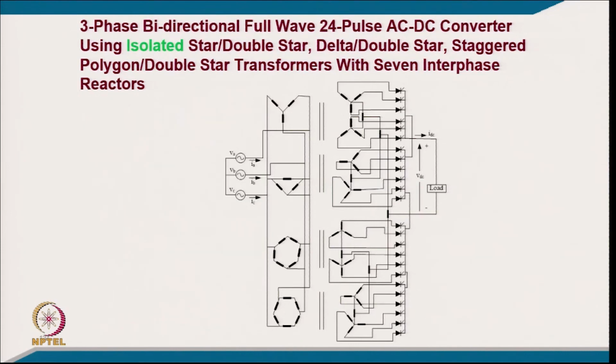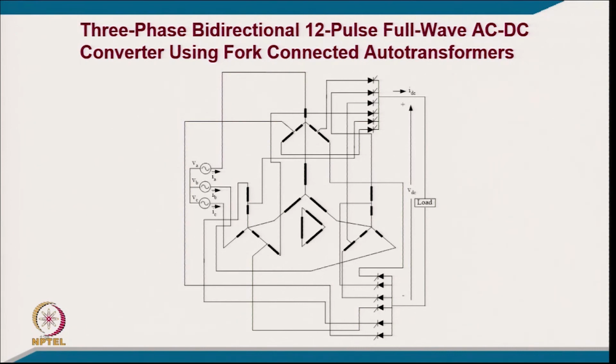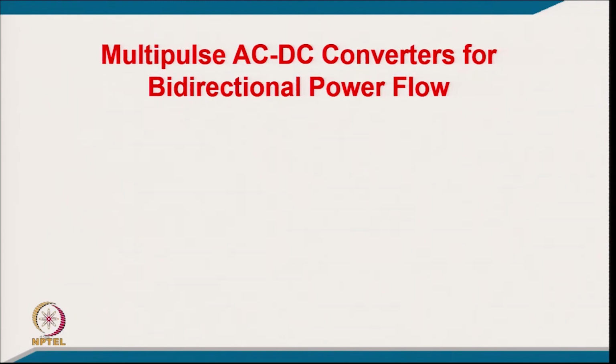And another is typically 24 pulse. So, you are converting 3 phase supply into 24 phase supply, and then you are using a thyristor converter for controlling, full wave converter. Only one thyristor comes in the path of the current, and you are able to get 24 pulse in the output. You get control of voltage, but at the cost of reactive power burden, but harmonics are certainly reduced, corresponding to 24 pulse. And this is again another connection of 12 pulse with the full wave, non-isolated category.